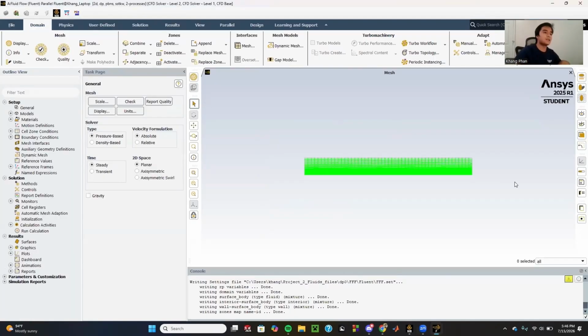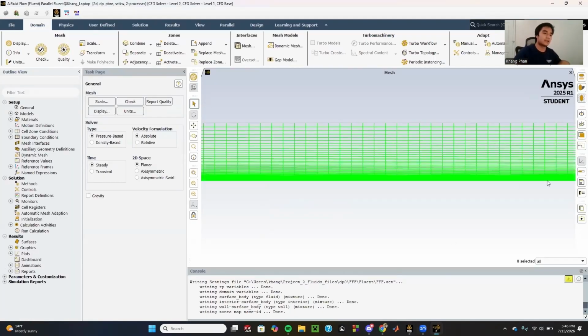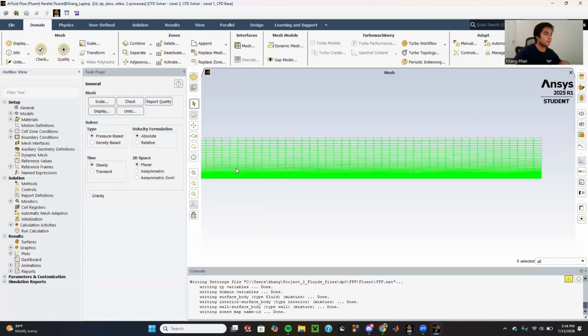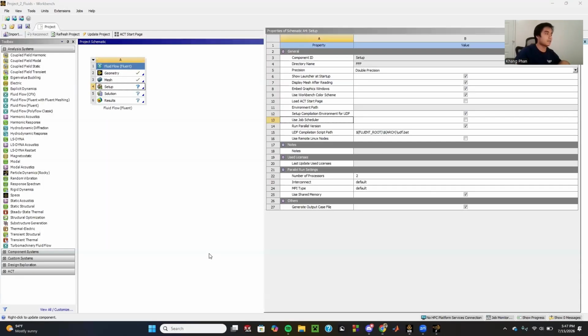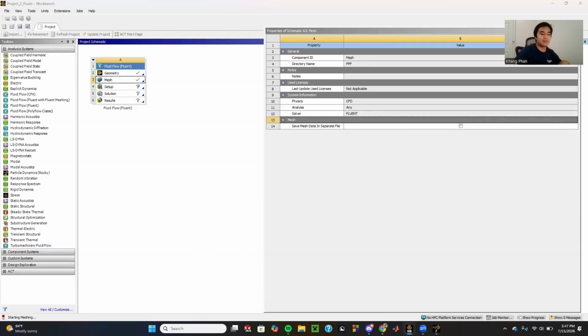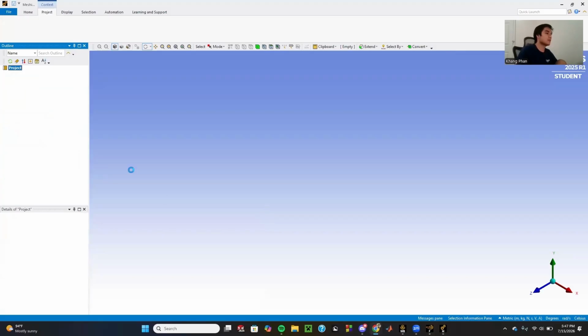At the time it loads, you should be on this screen. You can see the mesh that we did in green. Now I just realized that I forgot a step in the meshing process. So let's just double click this to get it back. I shouldn't have closed it. The thing I forgot was to name the things that we did. This is important because ANSYS actually uses these names to understand what everything is supposed to represent.